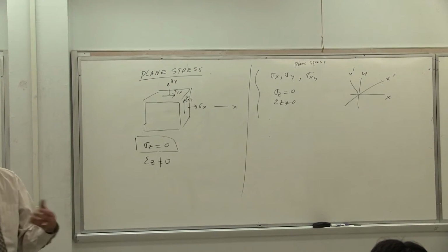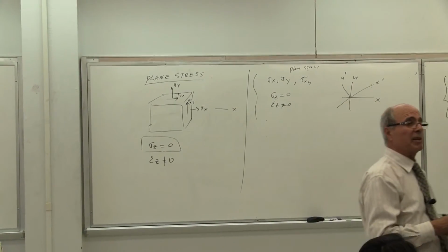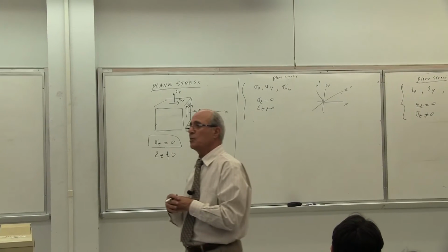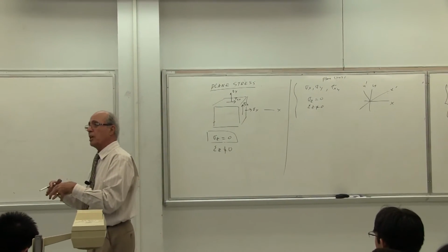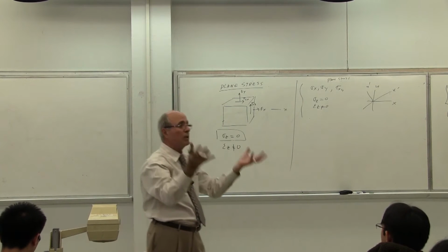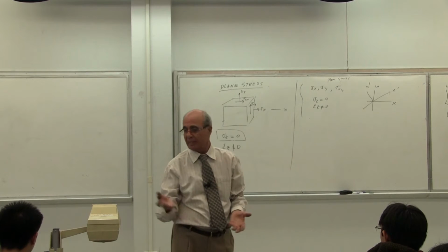Then you calculated those stresses, and you found out those stresses keep changing. Yes? When they kept changing, then it came to your mind, if it keeps changing, therefore somewhere else must be maximum. Yes or no? In order then to find the maximum, Mr. Mohr gave you a routine, that all the stresses fall onto the circumference of a circle. So we got the Mohr circle.